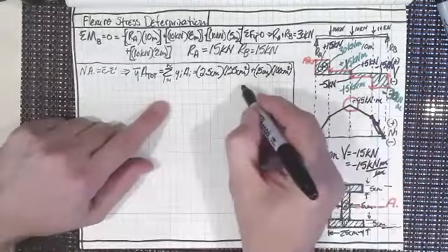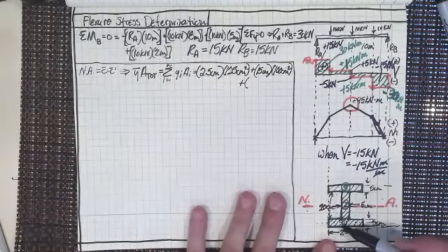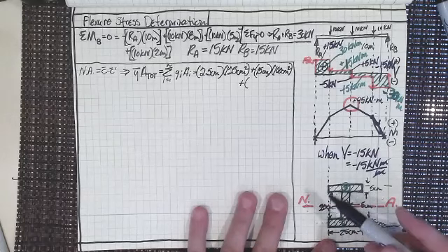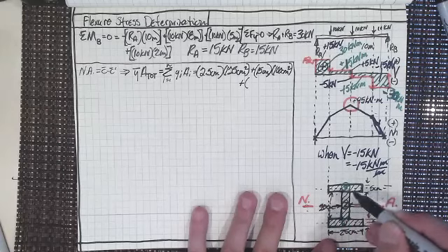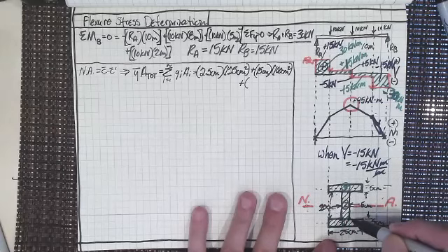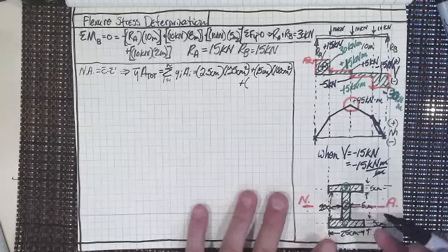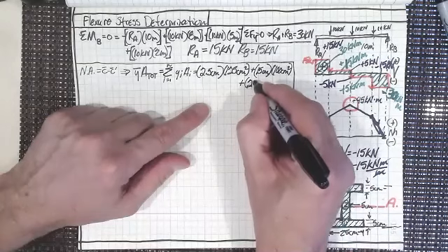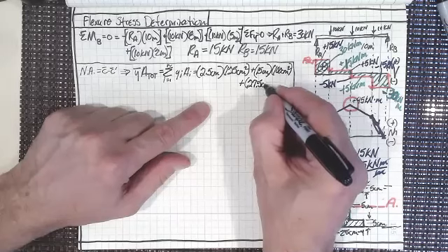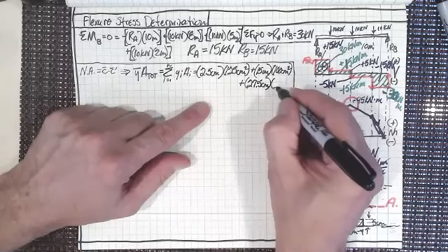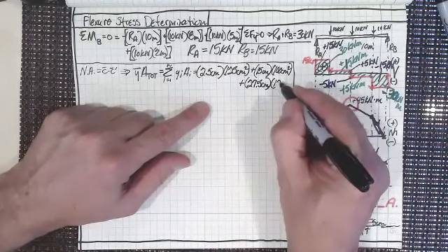And then the last one is going to be, well, where's the centroid here? Well, that's about 2.5, right? The centroid for this is 2.5 above where it is now. So let's see, 5, 20, 25 plus 2.5 gives me 27.5 centimeters times, well, 25 times 5, that's 125 centimeters squared.